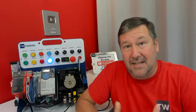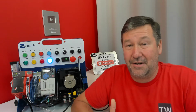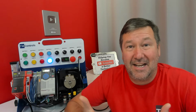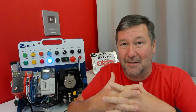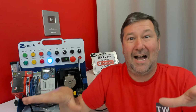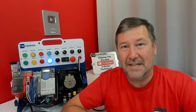Now, since there is not an industrial or a DHCP server out on your network, typically in a plant, then it's going to arbitrarily assign you an IP address of 169.254. Now, very important, this is more for the instructors. There is one training company out there that tells you to just do a DHCP, and then wait 2 minutes.